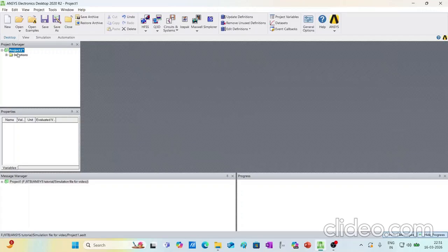So our objective is to model a permanent magnet machine in a 2D environment and to run the model in the transient simulator. So we want our result to be varied upon time, so we need the solver as transient.